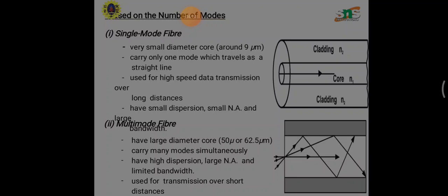The cladding diameter is also larger than that of single mode fibers. The structure of the multi-mode fiber: core diameter 50 to 350 micrometer, cladding diameter 125 to 500 micrometer, protective layer diameter 250 to 1100 micrometer, numerical aperture 0.1 to 0.5, and bandwidth less than 50 megahertz kilometer. For application, because of its lower bandwidth, it is very useful in short haul communication systems.